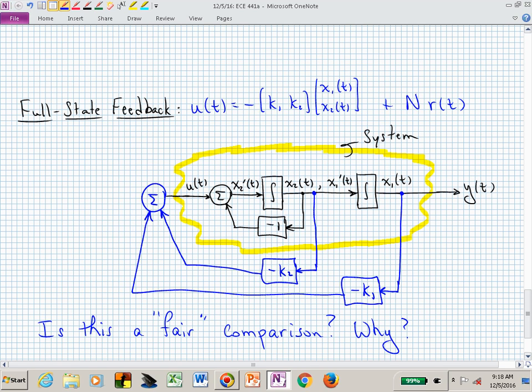And if we just wanted our system to respond to disturbances or bumps in our initial condition, this is all we would have to do if we didn't want to drive our system. If we just wanted it to respond to offsets in our state vector, we would maybe want y to always be 0. Then we've changed the dynamics of our system by the introduction of k1 and k sub 2.